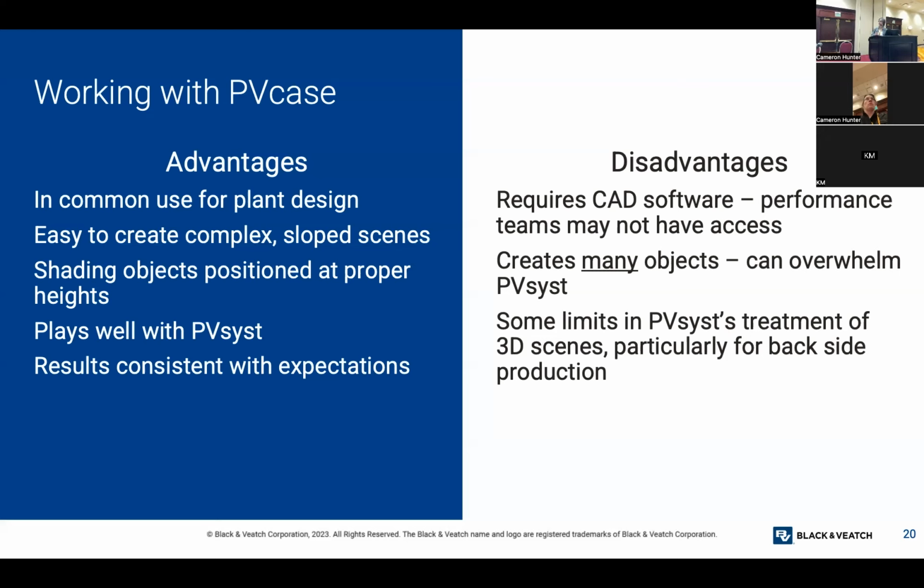And then finally, there are some limitations in PVsyst treatment of 3D scenes, which I guess were not really discussed, but particularly for the backside production, there's still assumptions made that don't actually include the terrain. So there's still progress that could be made in improving the modeling using the scene, but in general, it's been really helpful to us, and I think we might go in this direction.